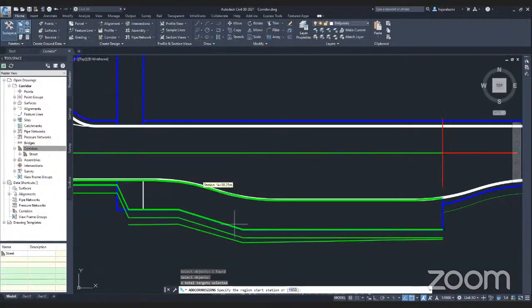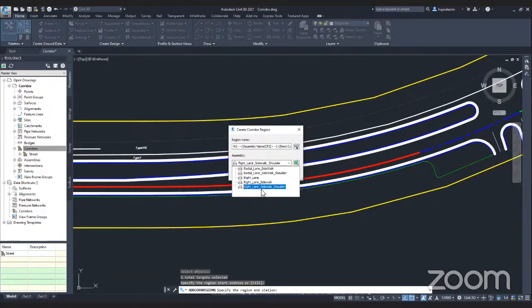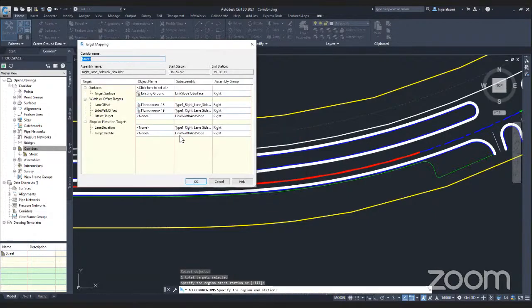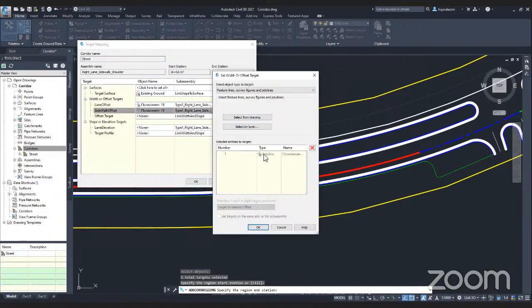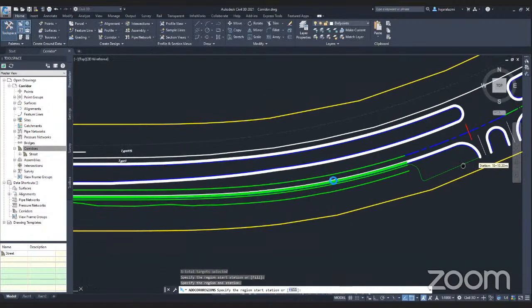And I'm just going to continue again drawing our corridor, right, up until there just now. So this will be the right wall with the shoulder also. Click on OK again, and then just continue from here. So this one, I just want to turn off the sidewall offset because we no longer want to have those shape according to what we have the sidewalk for the bus stop just now. So we just click on this line and then this shape, and then just click on it, close that, and I click on OK, and I click on OK that.